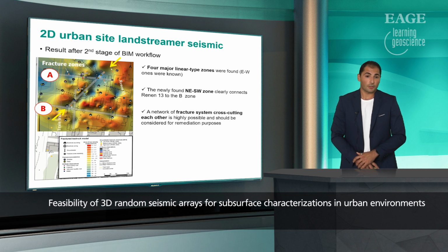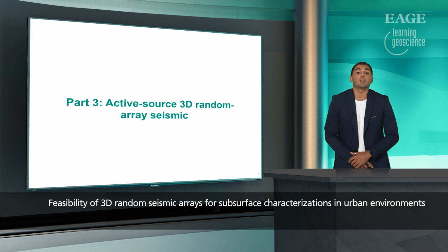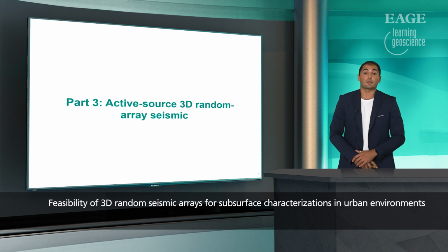The northeast-southwest one was previously unknown, and what is also possible is a network of fracture systems, and this should be considered prior to the remediation process. So we obtained a good velocity model and a good model of bedrock and bedrock weakness zones that has been tested and validated using the new drilling campaigns.